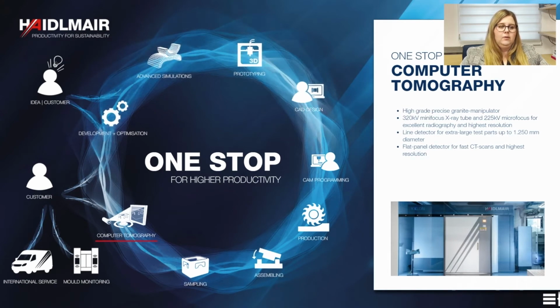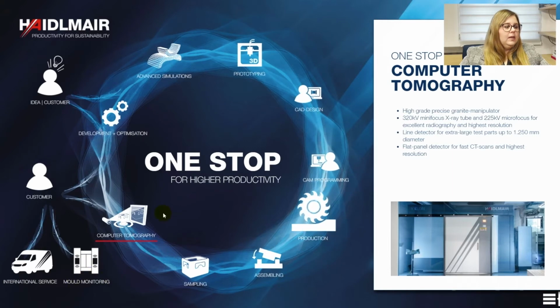That is my field of expertise, industrial computer tomography. Here we can evaluate optical defects, we can detect cavities, do metrological measurements, everything that we can see in a CAD design can be tested with computer tomography. If the client is satisfied, we can then deliver the mold.